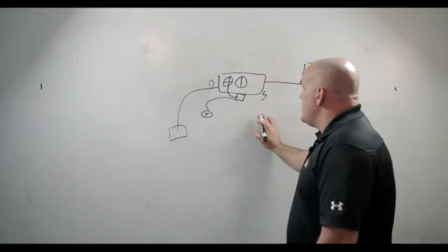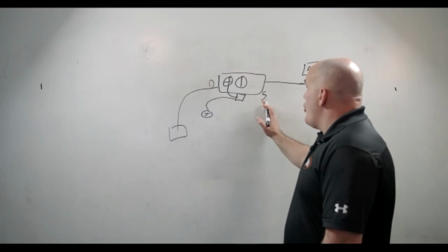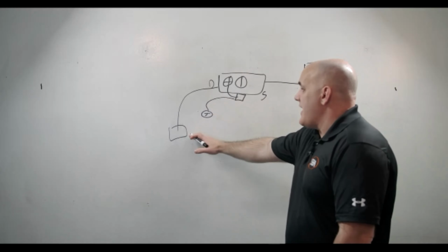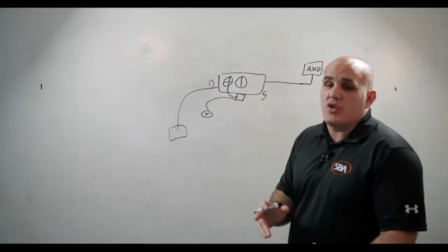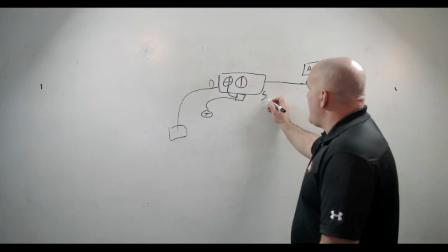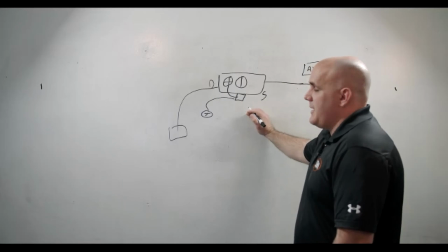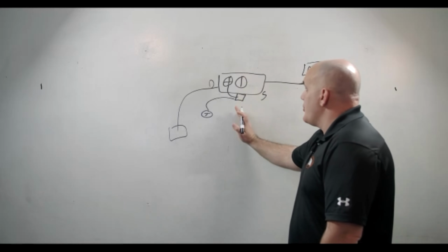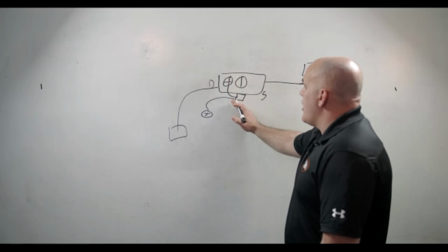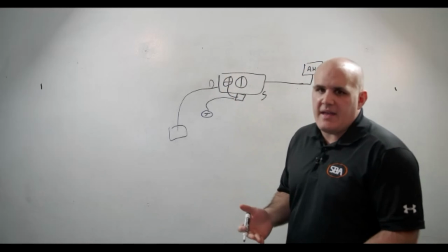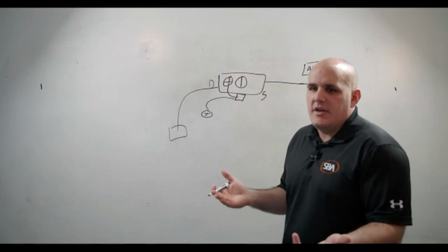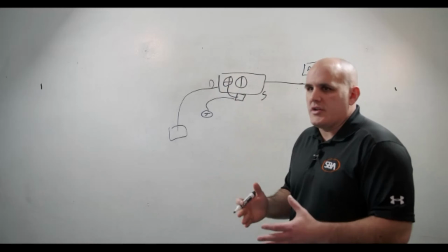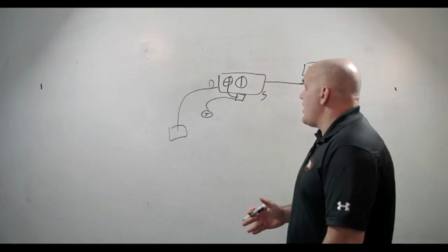The next thing we know is that, in order for us to get the supply air into the space in the right quantity, we verified we have air, we verified that it's the right temperature, we verified our actuator works. Now we're going to verify our airflow sensor works. We take a mag gauge, hook it up to the airflow sensor, check our DP, make sure it works, do some calculations, make sure we got the right air.